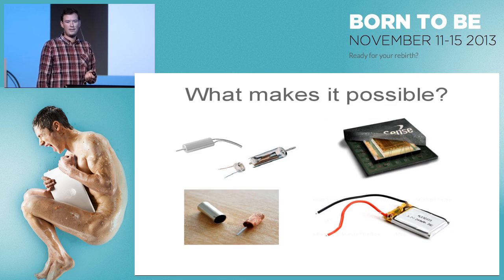So the final thing, what makes this possible, making this small one? Well, there are some key components, and one is the motors. They're called brushed coreless motors, and they originate from pagers for the vibration. They're just a coil and a magnet. There's no iron in them.